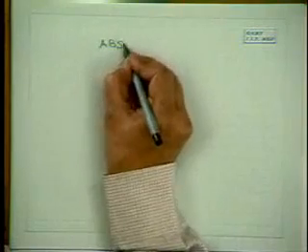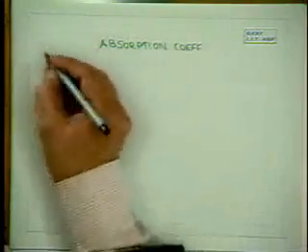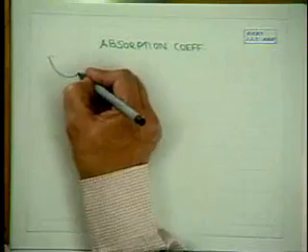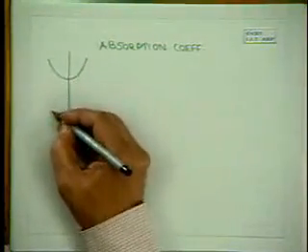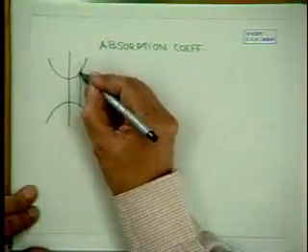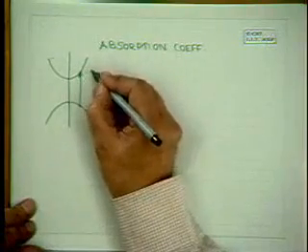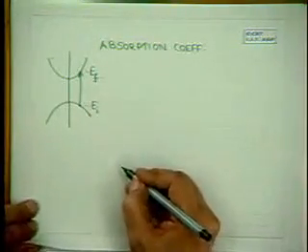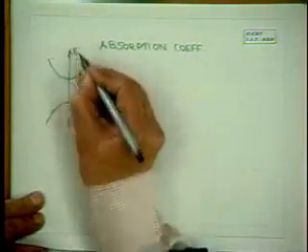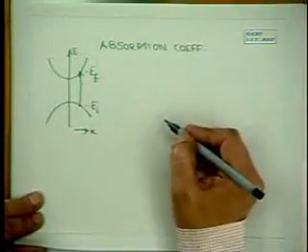Right. Now, if we go back to calculations of the absorption coefficient for a direct gap semiconductor, we have an electron at an initial energy EI being excited to a final energy EF, which has the same momentum because the momentum of the photon is negligible.